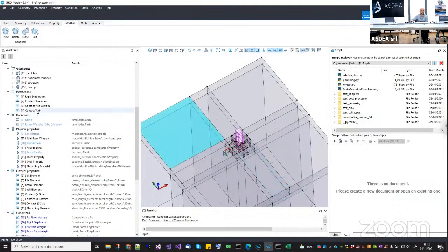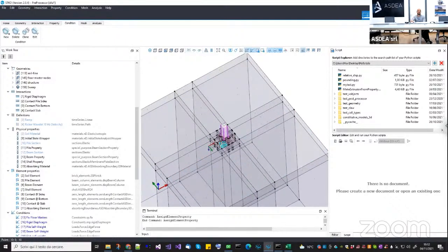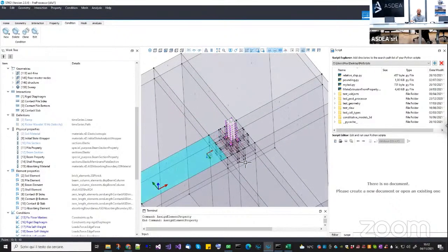Well, first you need a new interaction. This interaction should be a node to element, where the master is the element and should be all the surrounding solids, because it is the coarser mesh, and the coarser mesh typically is the master in a kinematic constraint. While the slave should be the nodes on the boundary faces of the detailed soil.